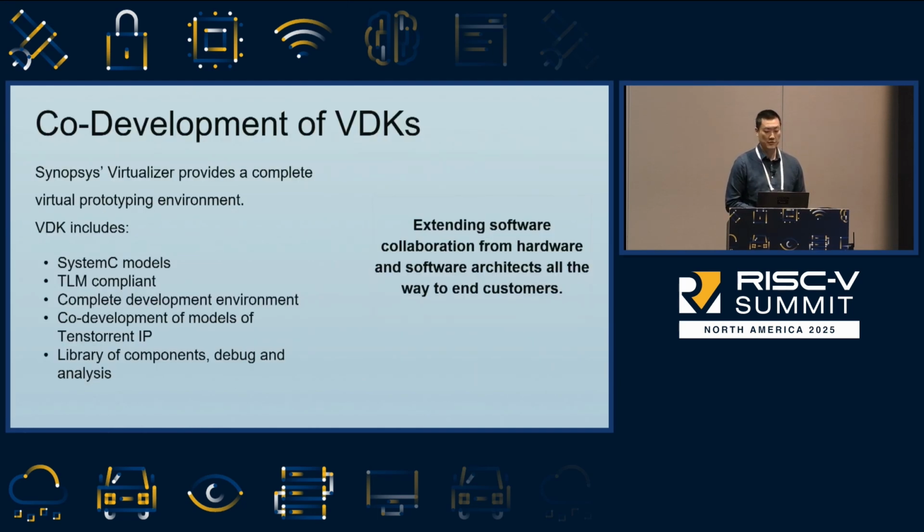We use Synopsys Virtualizer to help develop our VDKs for our complex systems. Virtualizer includes support for simulating SystemC models that are TLM compliant. We can co-develop functional models of Tenstorrent IP and leverage Virtualizer's library of components. Moreover, software developers can use the tool to help perform debug, write directed tests, and perform detailed architectural analysis.